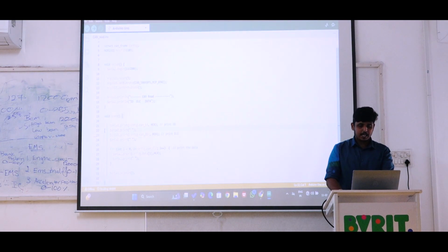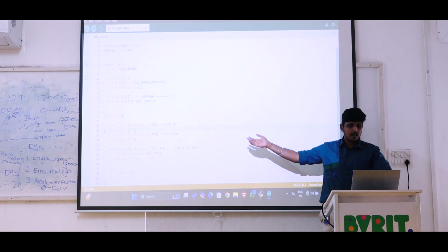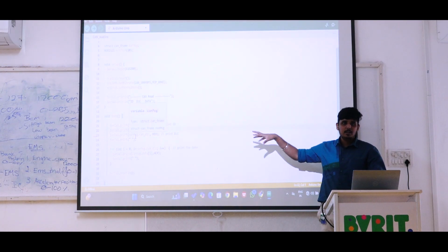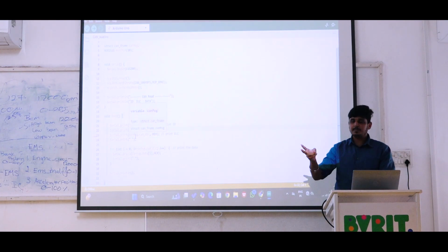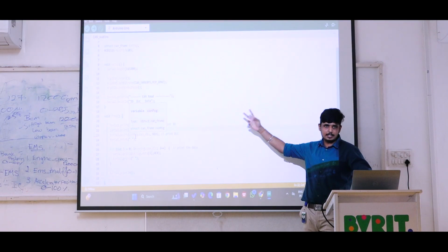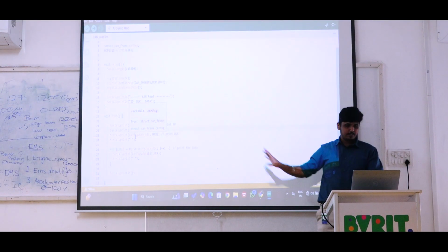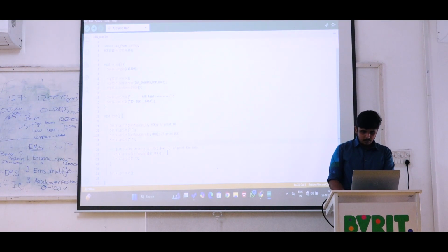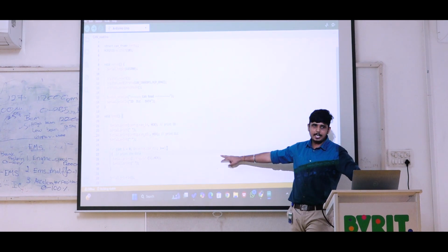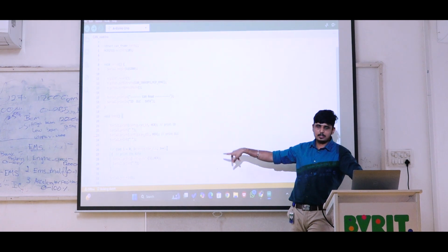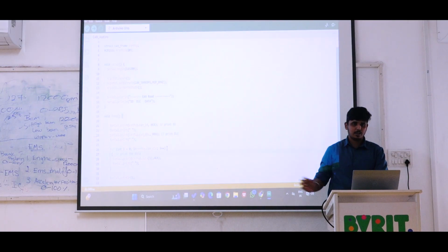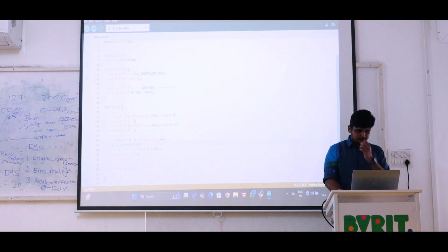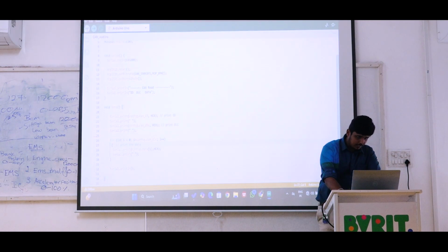We will check for the CAN message ID, which message ID is coming, and it is going to loop. If you are sending two message IDs, the first message ID will print first and then the second message ID will print within this loop. For that we are using an array for the first ID and CAN message two for the second ID. Like that you are going to get the sub IDs. For that just compile.